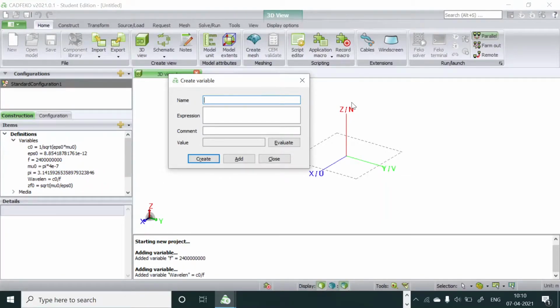The next parameter I want to define is the thickness. I will define it in terms of radius, and the diameter of the wire I want to choose is half an inch, so that is 0.635 centimeters. So half of that will be my radius. You can define the diameter first if you want, and then the radius. Both are fine, but you will have an additional variable to define.